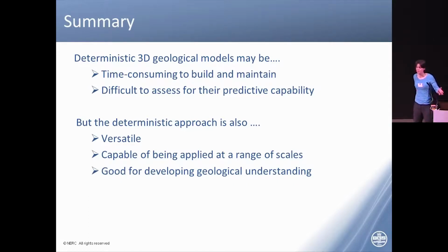Within the process of doing the modelling, because it's very strongly geologist engaged in terms of how we develop the models, one of the things we do is actually assess the data as we go, not necessarily in a standardised way, but as a geologist I have boreholes, I download them, I look at the logs, I'm trying to make sense of them in the context of the environment and the other material around it. So we are evaluating the information as we go along in terms of the modelling process.